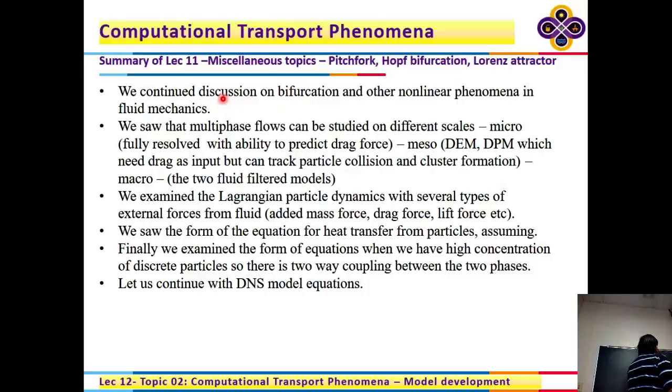So the equation that you're going to solve, there are three momentum equations. I was just writing it down. If you take the theta momentum equation, it will be something like this: dv/dt plus v dot del v equals, you need to expand this. It's actually not a bad idea. When I do a fluid mechanics course, I ask you to expand and solve it analytically. So minus dp/d theta, 1 over r, plus mu del square v. Now v is the v theta component. So this is the theta momentum equation.